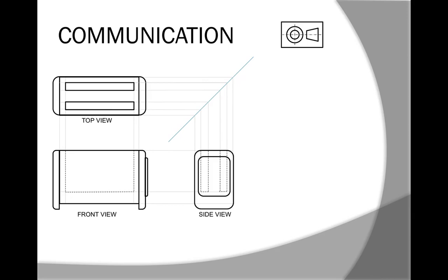Okay. Lastly, we've got this drawing, right? We've got a third angle projection. We can tell it's a third angle projection because I've got this symbol here. I know it's third angle because I've got the target and then the flag. If it was first angle, it'd be the flag, then the target. Yeah? Now, the flag is always drawn like a less than symbol. Okay? Now, what do we need to draw? We need to draw a top view on top.